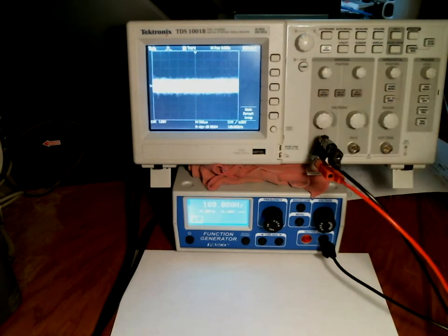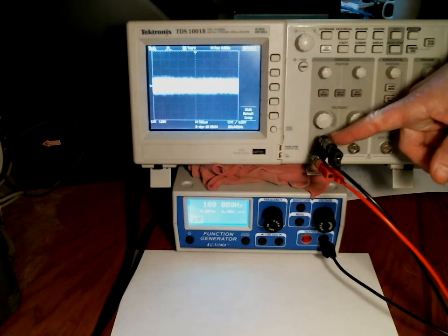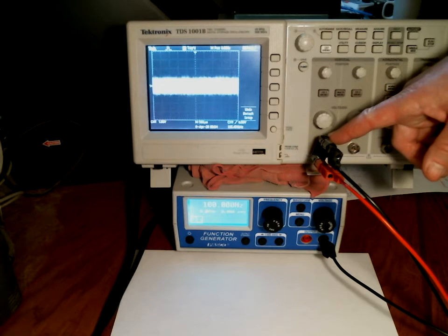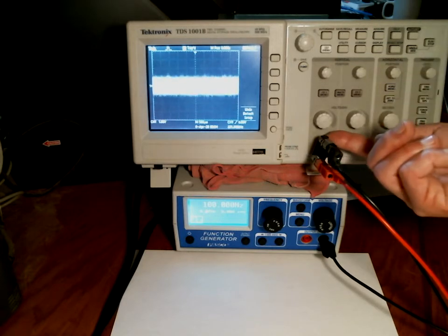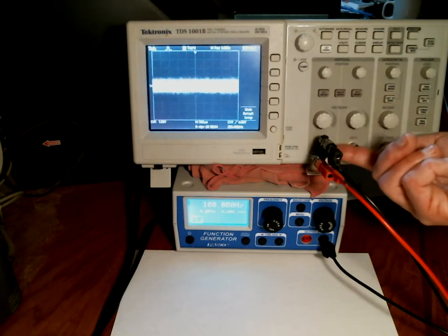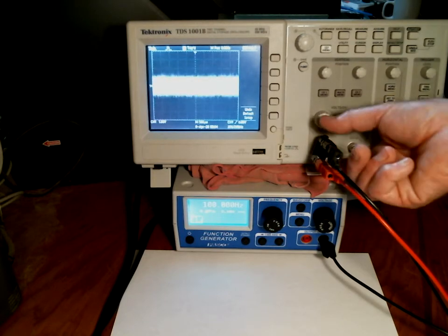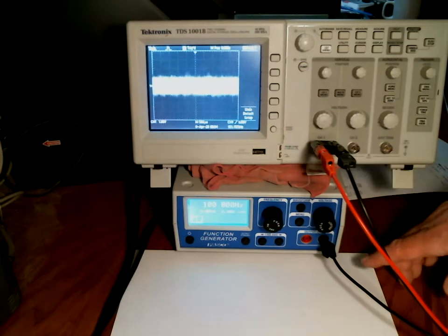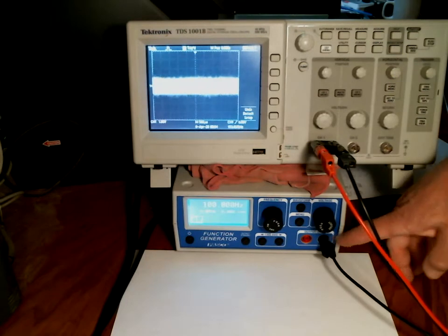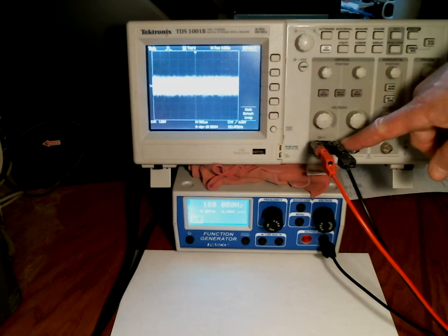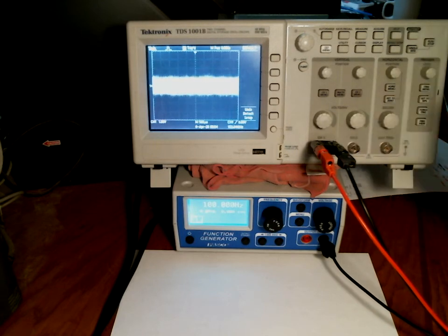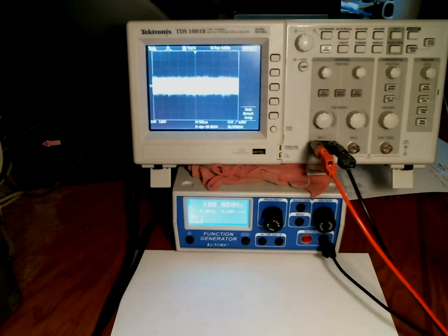because on this BNC to banana plug converter, it's labeled here which side is the ground, and there's a little tab there, and that means that's the ground supplied by this metal housing on the connector. That has to be connected to something that's also grounded. Since this is grounded and this is also grounded, if I were to connect something like the red cable to there, I would essentially be shorting across the inputs to the scope.